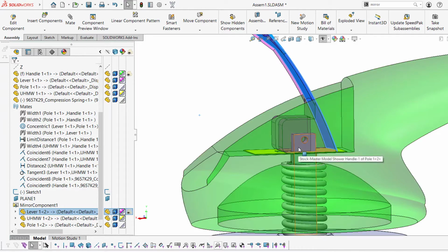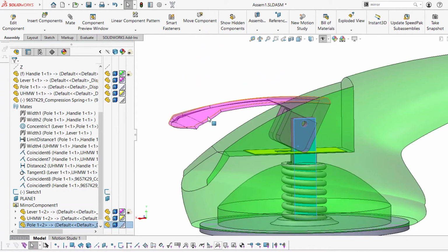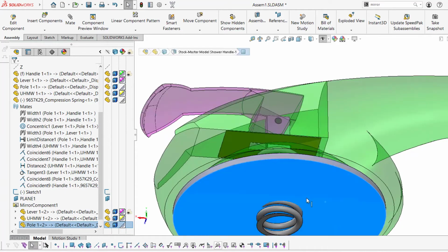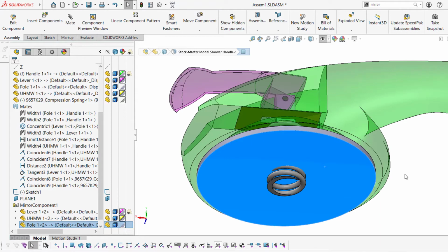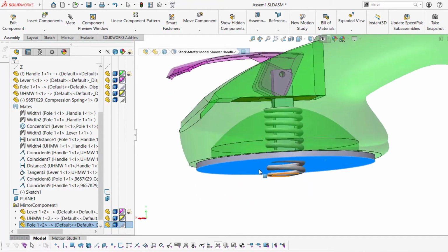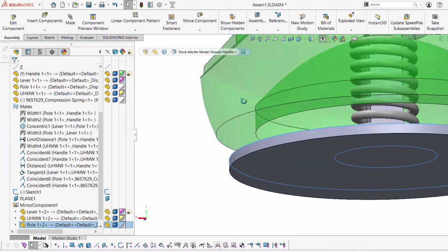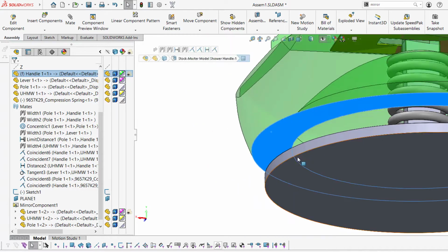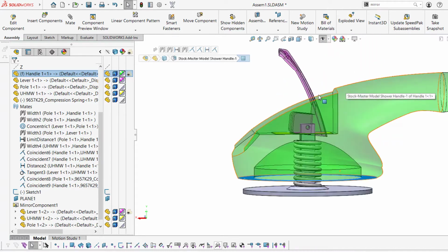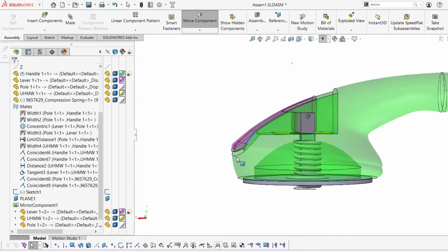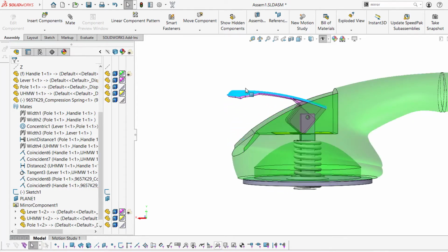So you basically want to move the rod up by actuating the handle, because when you move the rod up, we want to move the suction cup up because it's going to create a vacuum here. The air particles will escape. There's going to be less air particles, and we want this edge face right over here to come in contact with this face so we can seal the edges so no air can escape the vacuum or go in, vice versa. Very simple mechanism. One more time. Up and down.